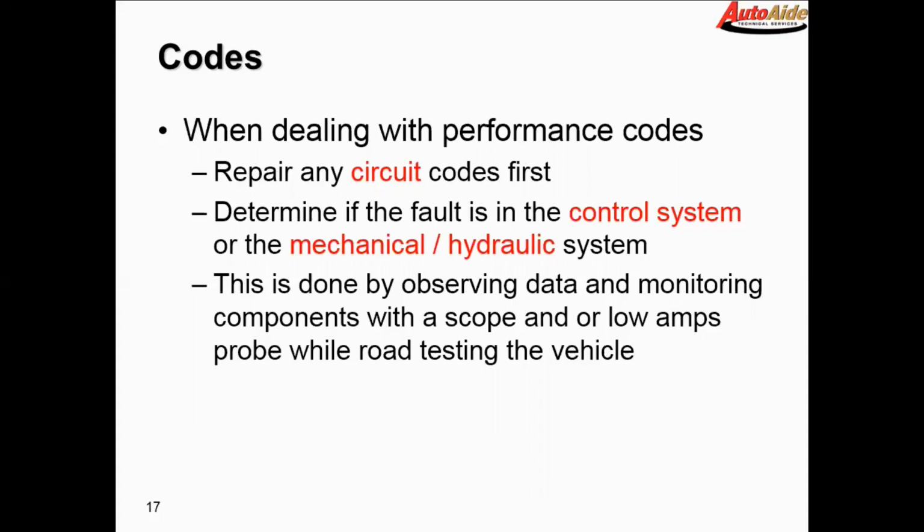So how do you sort of separate it out? This is done by observing data and monitoring components with a scope or low amps probe while testing the vehicle. And just let me give you one more thing on this: you can have problems with solenoids and that kind of stuff that don't set codes.